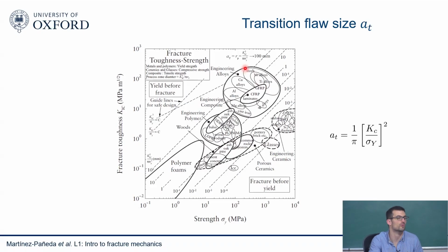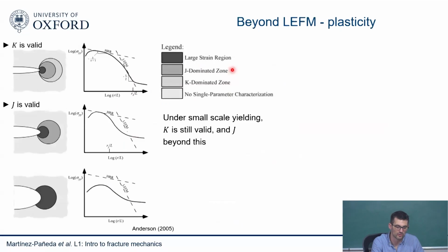We want to put obstacles to plastic deformation, whatever obstacle you think, carbides, whatever you think to increase your yield stress, to lower plastic deformation. And of course, plastic deformation also gives you toughening. The more plastic work, the tougher your material is. So by putting obstacles to plastic deformation and increasing your yield strength, you are lowering your fracture toughness within this class of materials, steels. Okay, anyway, so this is the key point.